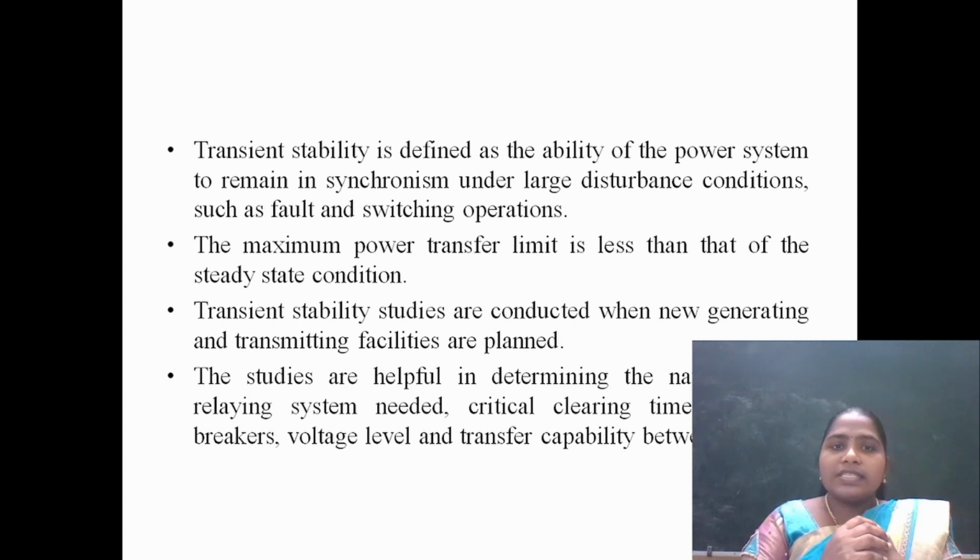The transient stability studies are conducted when new generating units and new transmission units are planned, and these studies are helpful in determining the nature of protective system needed, critical clearing time of the circuit breakers, voltage level as well as the transfer capabilities between the systems. So overall, in the planning of a power system, we need various analyses: load flow, short circuit as well as stability.